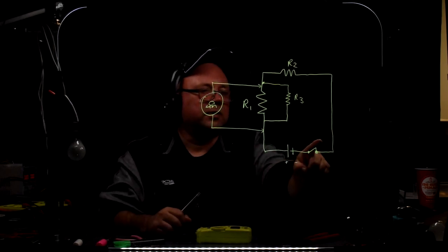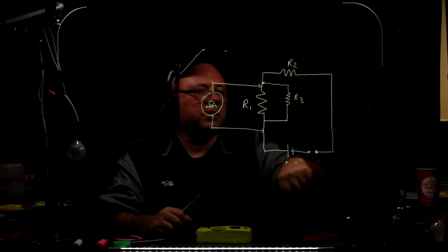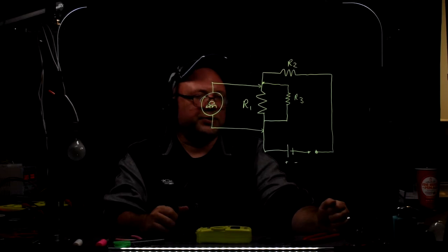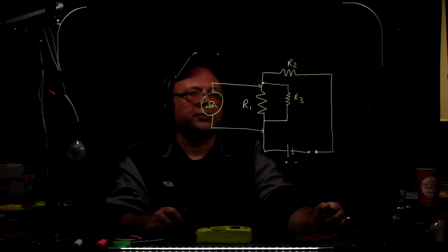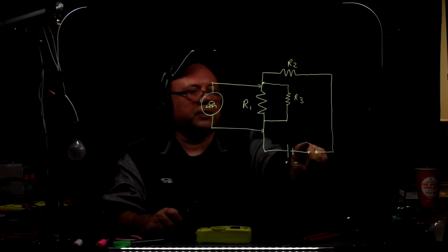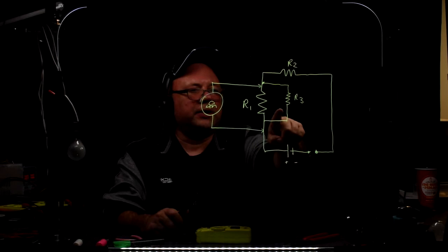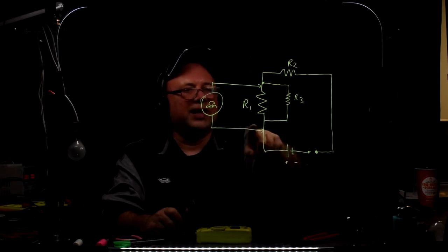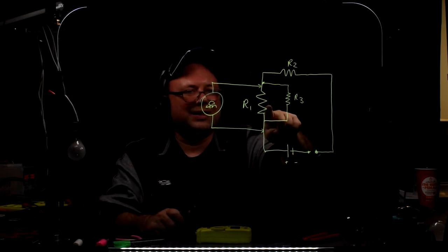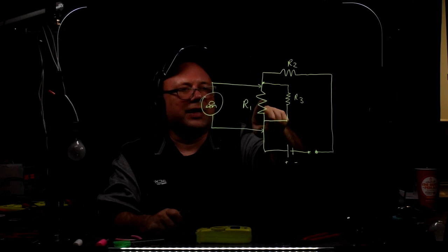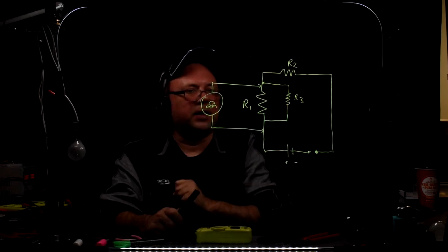Okay? So first we need to de-energize the circuit. So we're going to open the switch. Okay? Now there's no current flow. The circuit is de-energized. Can we measure the resistance of this R1? We still can't, because even though there is no pathway going here, there's some other thing that is connected to this resistor. So if you just want to measure that resistor R1 value, we need to disconnect that from the R3.